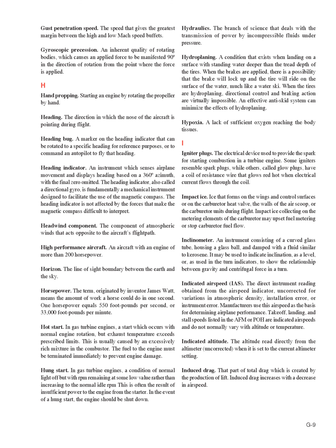Hydroplaning. A condition that exists when landing on a surface with standing water deeper than the tread depth of the tires. When the brakes are applied, there is a possibility that the brake will lock up and the tire will ride on the surface of the water, much like a water ski. When the tires are hydroplaning, directional control and braking action are virtually impossible. An effective anti-skid system can minimize the effects of hydroplaning. Hypoxia.